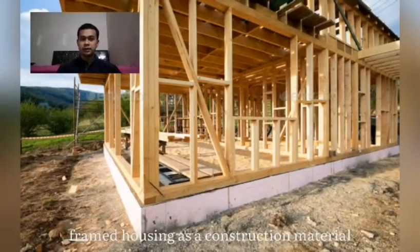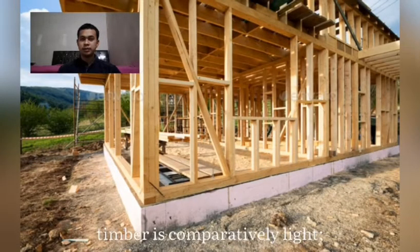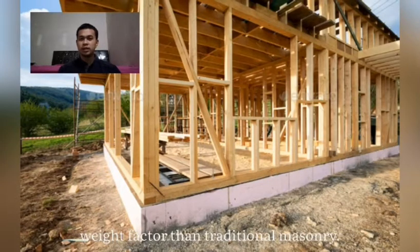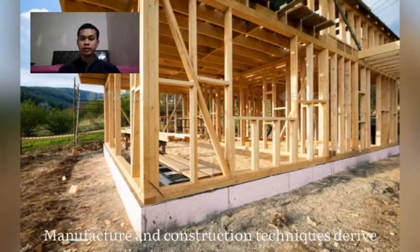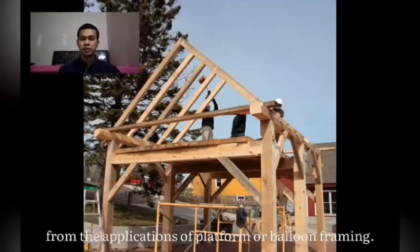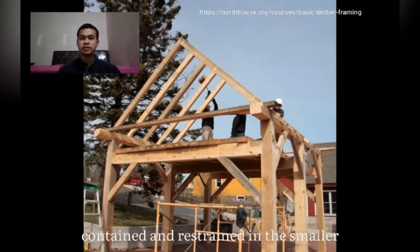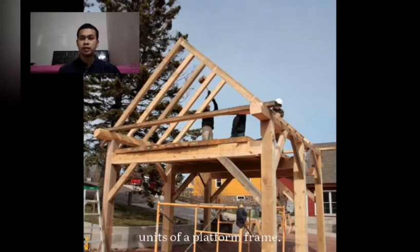Framed housing. As a construction material, timber is comparatively light. It is therefore easy to handle and is less of a structural dead weight factor. The traditional masonry manufacture and construction techniques derive from the application of platform or balloon framing. The effects of timber movement are more easily contained and restrained in the small units of a platform frame.